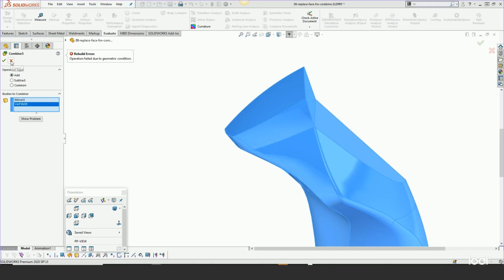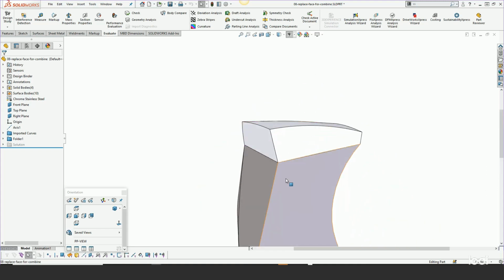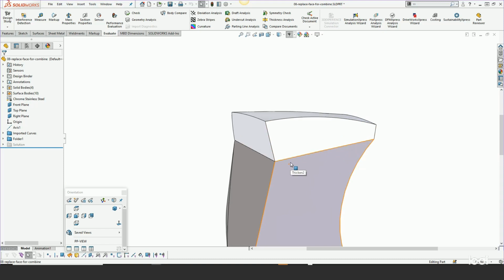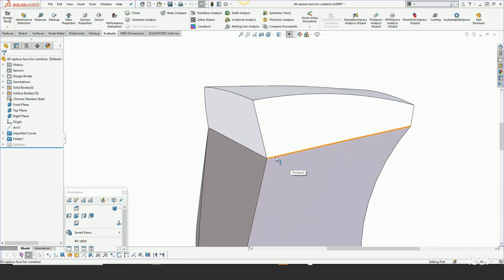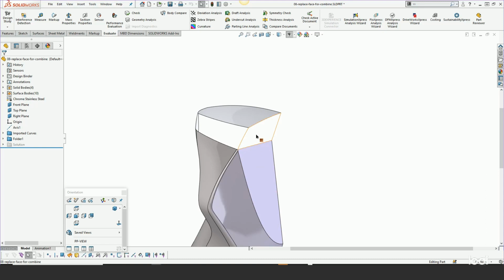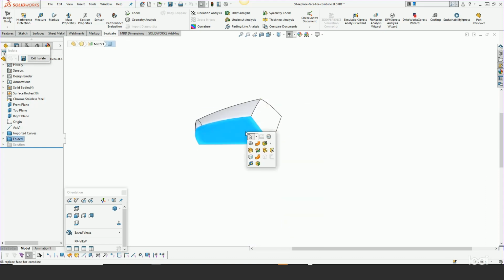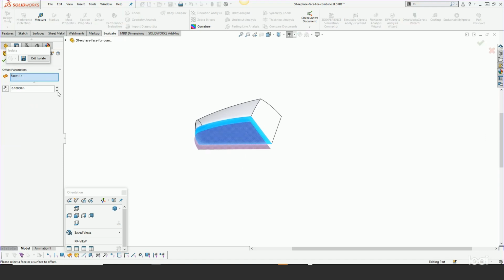But in this case, I don't want to really go back and change anything. So I know that these were built on the same face. It's just that they're not meeting each other, and there's probably a zero thickness error here. So here's my method for resolving this issue. If we isolate this model and basically just go here and create a copy surface. So offset with 0.